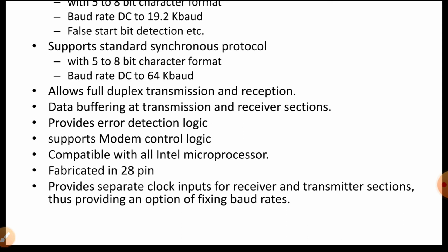It supports modem control logic. It is compatible with all kinds of Intel microprocessors, and it is an integrated chip having 28 pins, and it provides separate clock input for the receiver as well as for the transmission section, thus providing an option for fixing the baud rate.